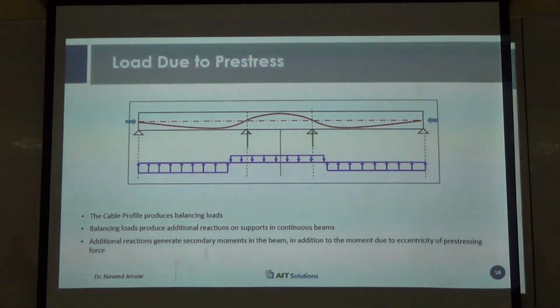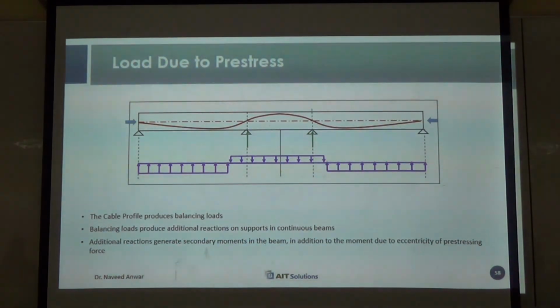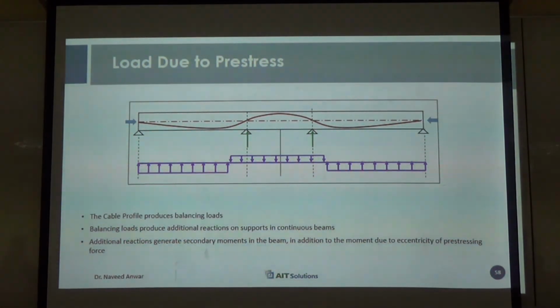In another 2-3 years, it might become flat. But in the beginning, it used to be more. Now it has become less. Now when I drive, I can feel it less. I used to feel it much more 3 years ago, 5 years ago. So that is something that has to be done: pre-stressing stages, and then long-term effects and deflections and what load is applied. If they remove the surfacing, the bridge will go up. Right? So a certain dead load is needed to keep it straight.